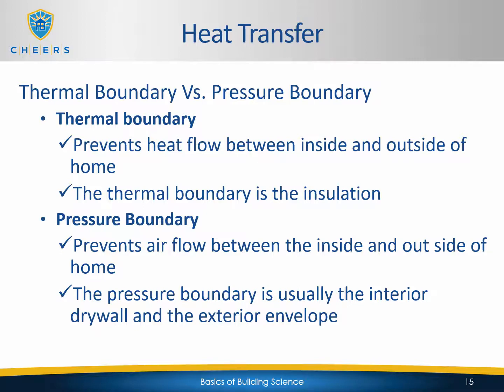So depending on the structural complexity of the house, the simple drywall that you're seeing from the inside of the house doesn't necessarily mean that is the pressure boundary. The main way to know whether that is the pressure or thermal boundary is that the insulation, as I'm going to talk about in the next slide, always needs to be in full contact with the pressure boundary. So thermal boundary and pressure boundary should always be together.